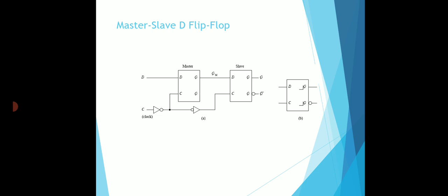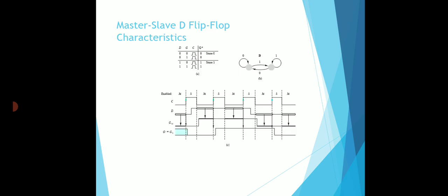Now it takes place for the clock cycle. When the clock pulse becomes high, the master becomes operational but not the slave. So the output of the slave will remain low while the clock remains high. When the clock is low, the slave becomes operational and it remains high until the clock again becomes low.